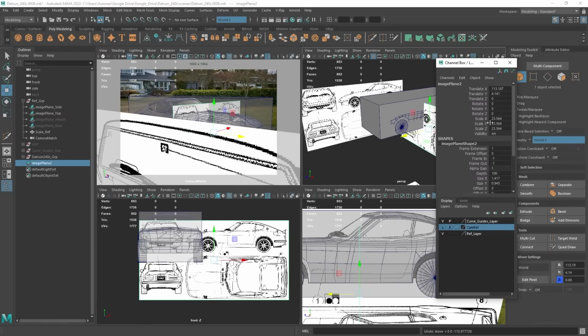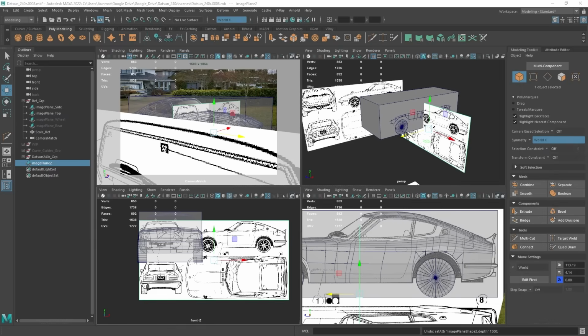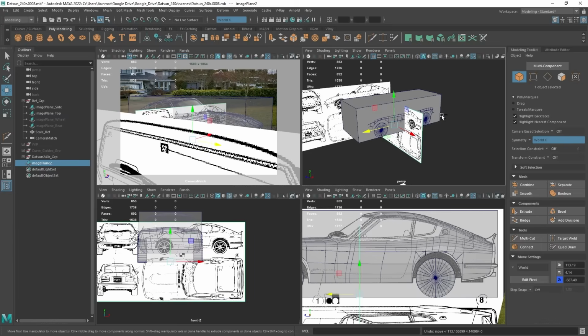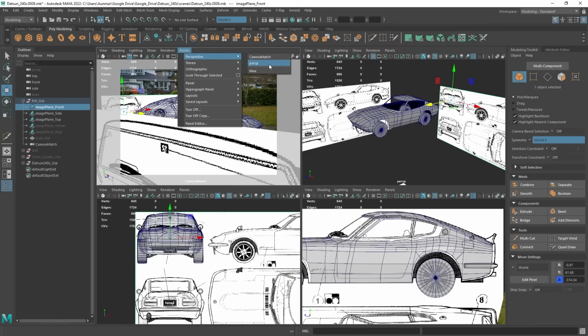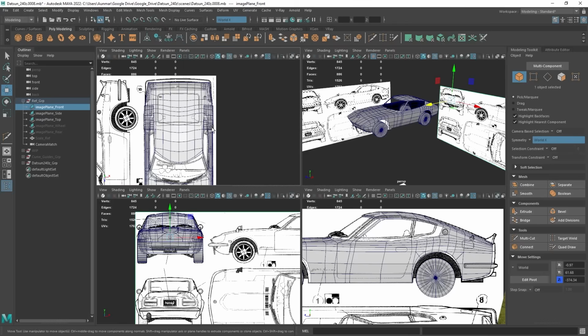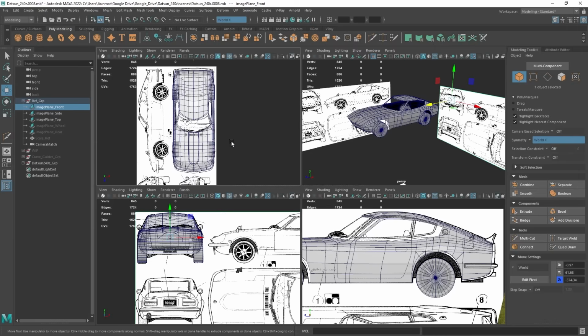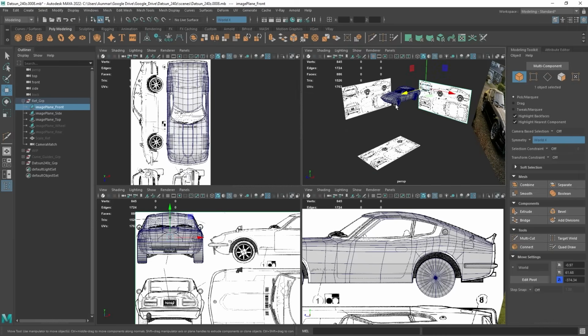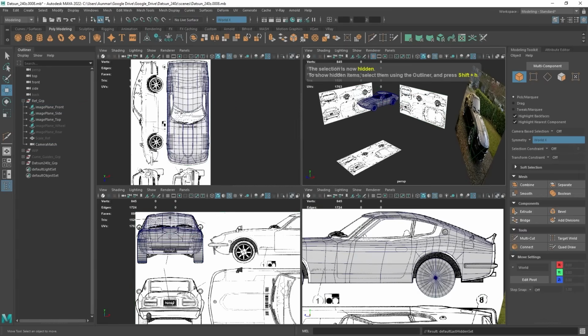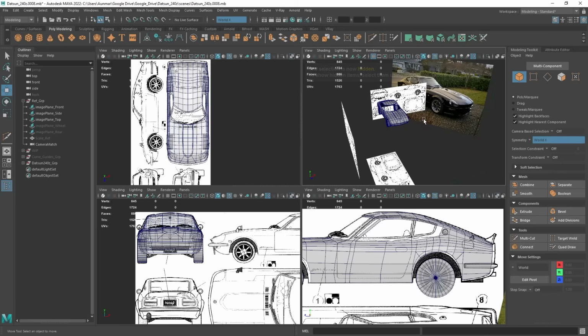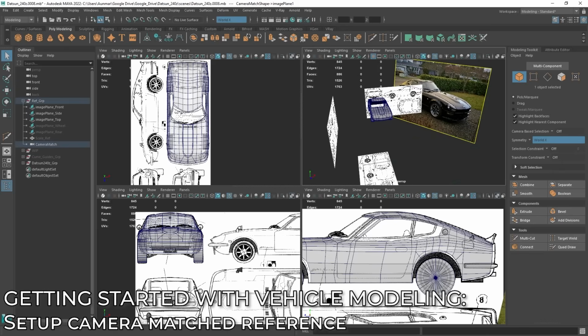And the other setting that I typically use is depth, where you can maybe type in 1500 depth, and you can see that also will push that back in your orthographic views there. But you can simply move that out. I'm going to actually just undo that and bring mine back to its original state. And I'm just going to do that for all of these orthographic views. You can see that I have this orthographic top view already set up by default, and that's already here. All right, so everything's set up, everything's moved in position, and I have everything to scale based off of this scale reference.